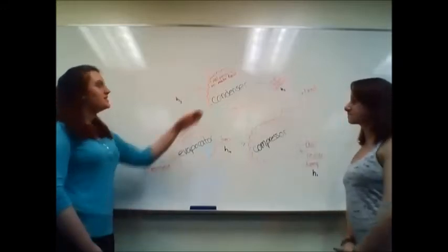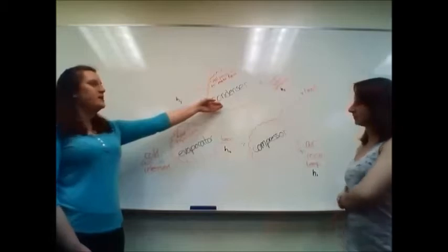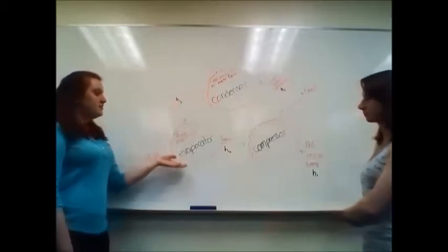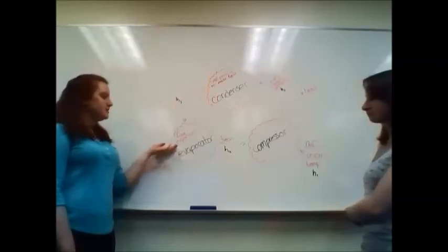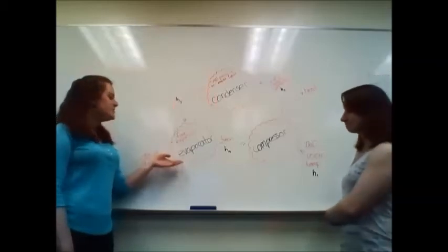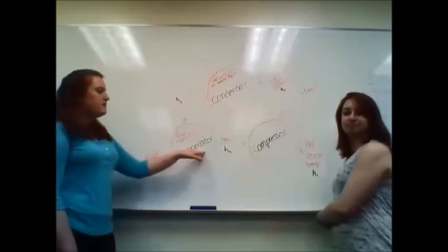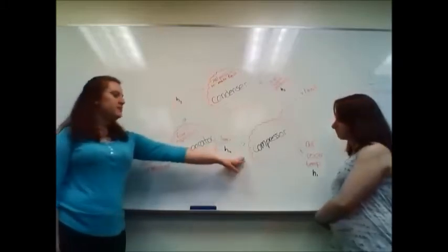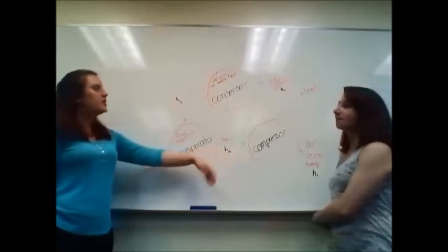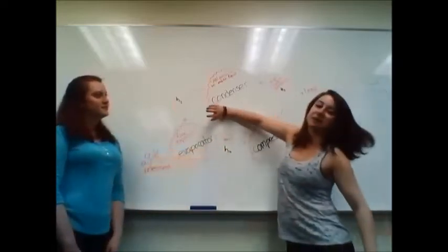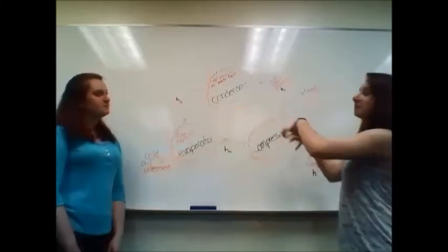So once it's in the condenser, it becomes a liquid, and that leaves with a new enthalpy of H3 and enters the evaporator, where it undergoes free expansion to turn it back into a gas, and some of it is released as cold air back into the room, and the rest is returned back into the compressor with an enthalpy of H4. And if you were to have a window unit, then your window would be sitting right here, and this would all be happening inside it.